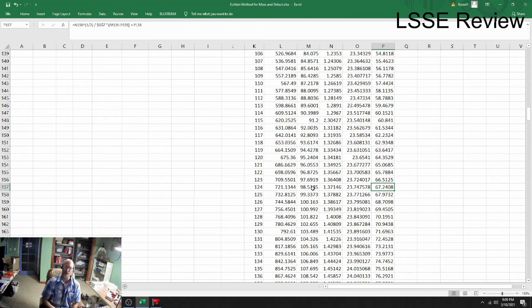In this case, it's 165 degrees. So I probably want to go with something a little bit lower. So this is how you approach things to get this balance in terms of how do you protect people by having a heat detector for a given fire design for your combustible loading.